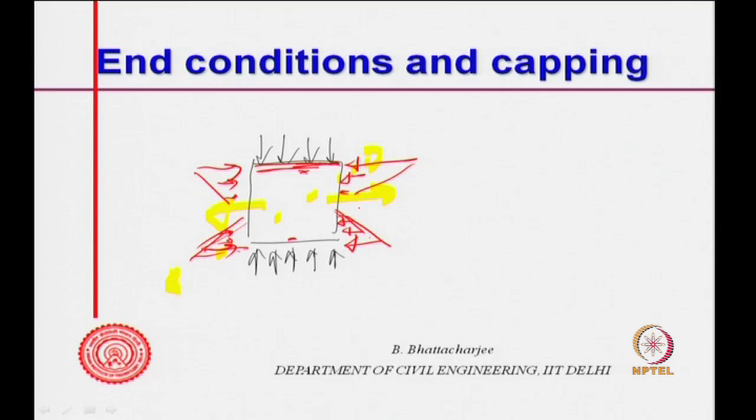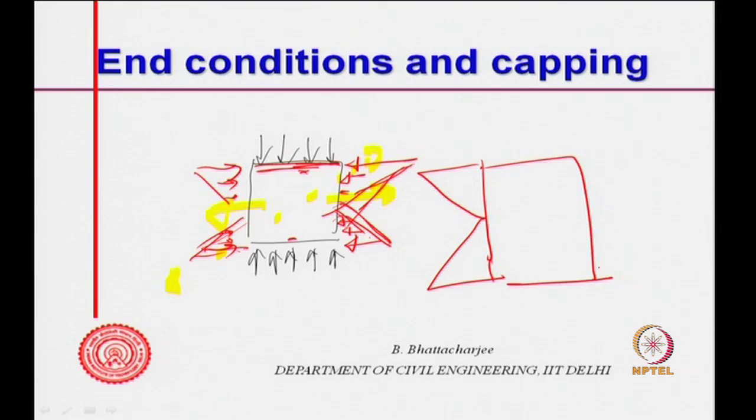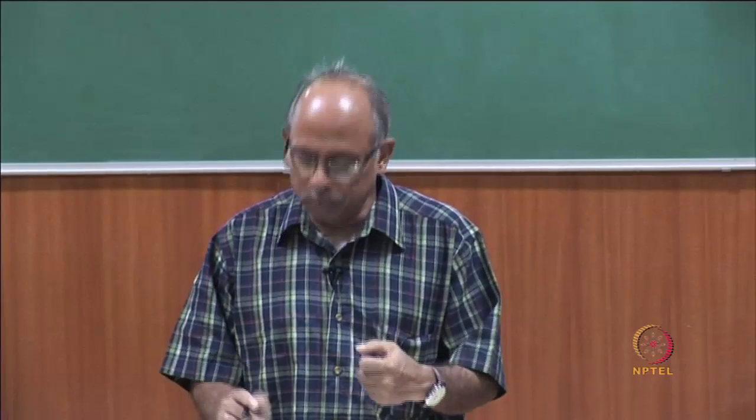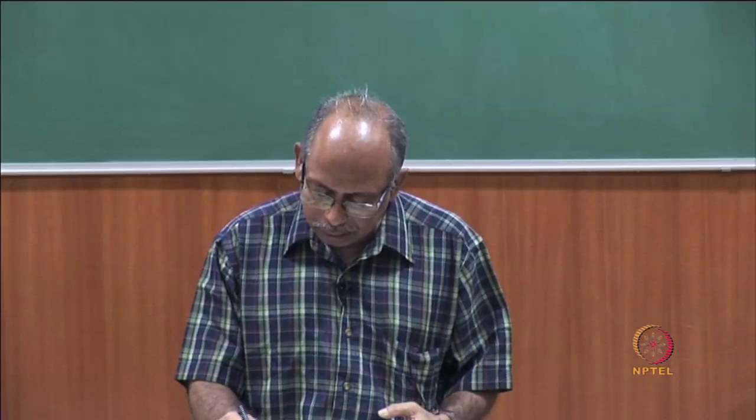So, you do not really have a purely uniaxial situation, you have a situation where there is some sort of force acting onto the specimen, depending upon the type of specimen or L by D, up to some height. There is a force acting like this also, and this will depend upon this L and this D, where D is the dimension of the cube. So, if it is D and D, then there is somewhat of an overlap, we will come to that just now. So, you see there is an opposing force to the horizontal or transverse movement, in both this direction as well as this direction.